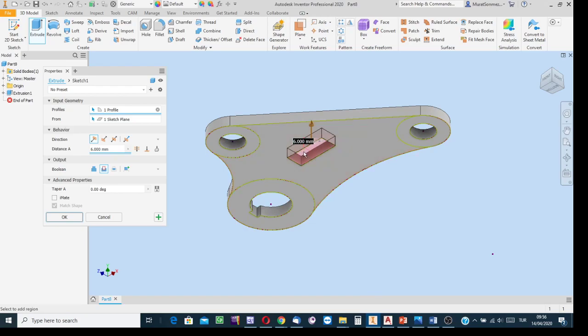But when I indicated the already used sketch, in most cases Inventor offers cutting because it is solid. Logically, Inventor may offer such a case, to cut the material. No. If this button is selected, the process is applied for cutting. Select the other join option, which is to add material.